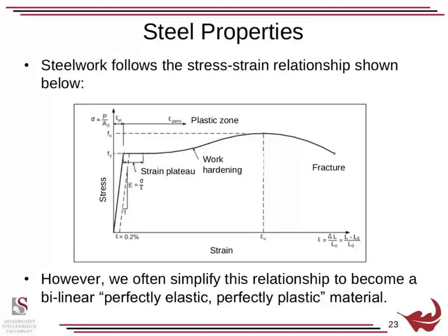Now, here is the typical stress strain curve. We start unstressed, we load it up, we load it up, we load it up, and then we hit our yield stress, where it more or less starts becoming linear after that. We keep loading and loading and loading. There's work hardening, and then finally you have ultimate. And that's the point of maximum load it can carry. It will start losing capacity after this, and then eventually get to fracture.